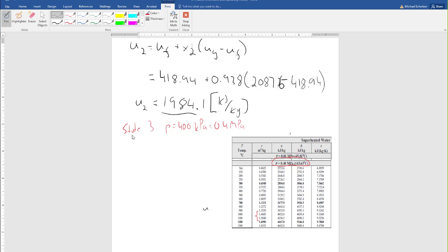Now I can define my interpolation factor A: I'll take the number that I know, 1.57 minus 1.4685, divided by 1.584 minus 1.4685. Again, on a test, I might just take this value at 1100 because it seems pretty clear that we're going to be a lot closer to this 1.584 than we are to 1.468.